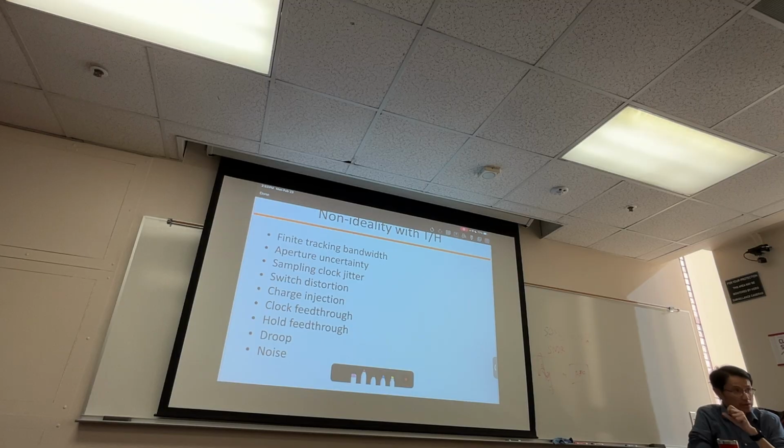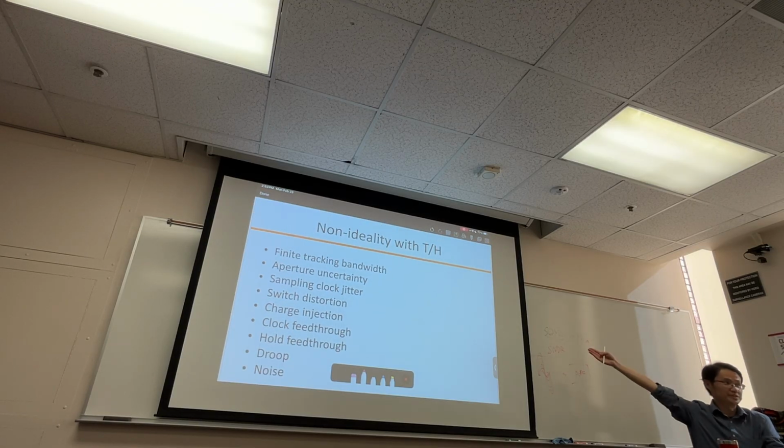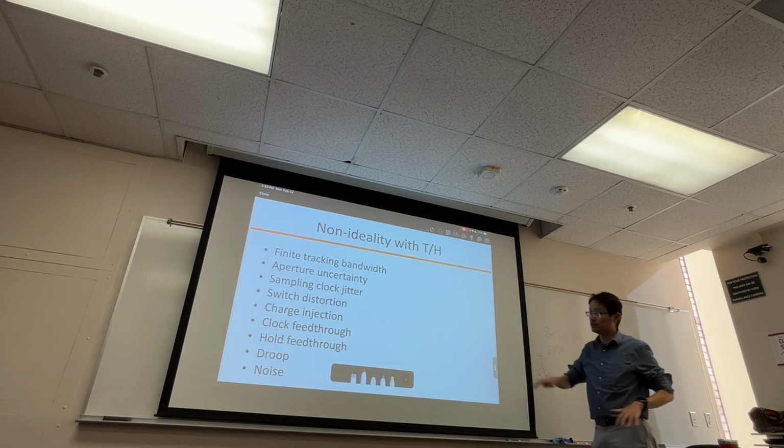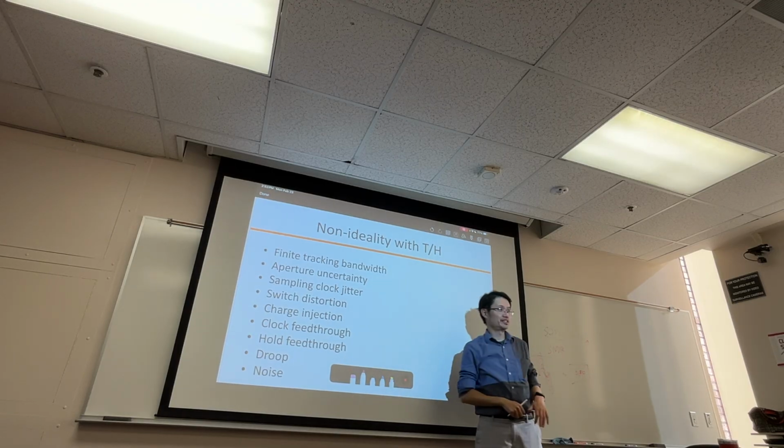One piece of good news is that this sampling circuit or track and hold circuit is not just used in ADCs. A lot of mixed signal circuits, have you heard about switched capacitor circuits? Switched capacitor circuits just come down to track and hold. All those switches are track and hold, and they have exactly the same design considerations.